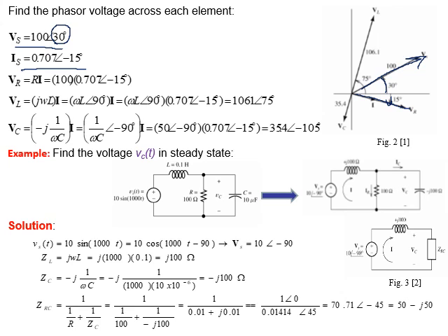Now I want to plot the voltage across the resistance, across the inductance, and across the capacitance. The current flowing through them is the same, so we just need to multiply that by I. R by I here, we got this. ZL by I, we got this. And for VC, ZC, which is minus j1 over omega C, by I, we got this. I will just focus on the angles.